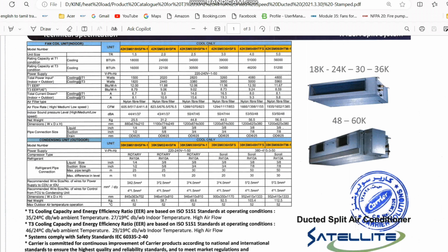So the second option we need to go to is this one, 1070, because as I told, airflow rate selection should be done on the medium capacity. So 1070 CFM we need to follow. What will happen is the unit capacity will go to 2.5 ton.